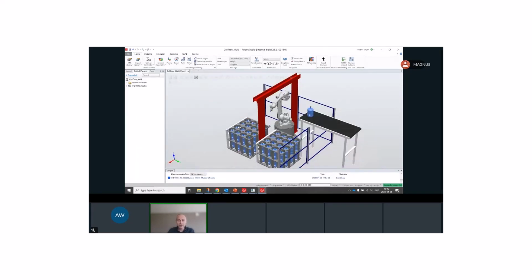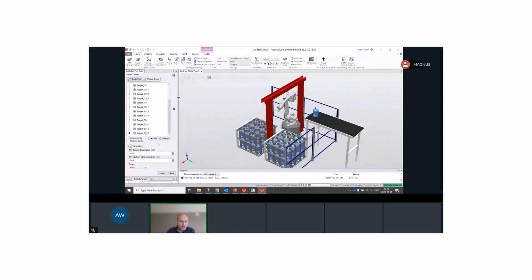The other one is this one, where we actually can plan for multiple targets. So in this case, I will use this robot. I will start from here, and I will visit all these targets here. Pretty much just the same example as before. So I just select the targets, I open up the path planning, and you can see we have a single path. And I will also make sure that I return to home after I visit all the targets here. So we go from home and visit all of them, and I just press create.